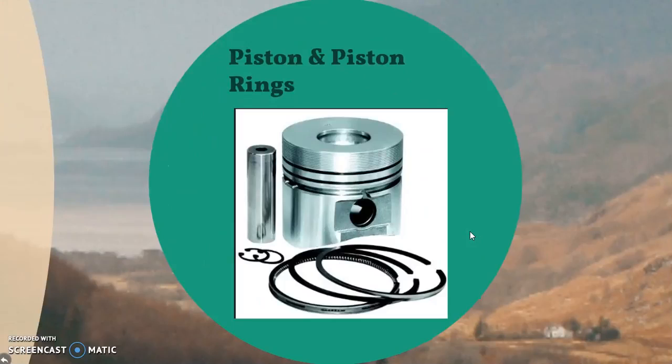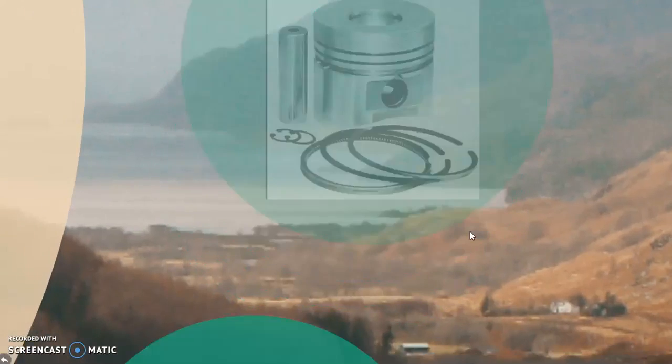So as I have already described what a piston is, that metallic block that slides up and down the cylinder. Piston rings are the small rings present inside the piston. They have a certain important function. For instance, the piston ring is responsible for preventing the fuel air mixture and exhaust in the combustion chamber from leaking. Also, they keep oil in the sump from leaking into the combustion area, which could otherwise prove to be very dangerous.